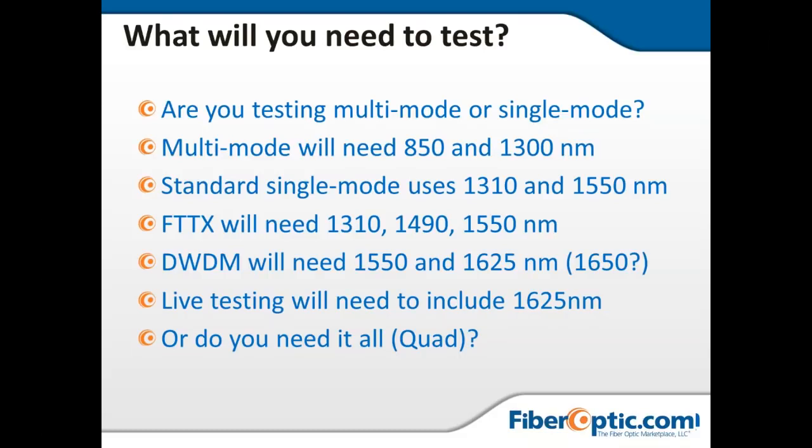From the house, we're typically going to shoot up towards the head end. Any information we need to send back, we will transmit at the 1310 nanometer wavelength. So you've got the 1490 coming down and the 1310 going back up the same fiber. Those two different wavelengths allow us to use the same fiber and transmit data in two directions.